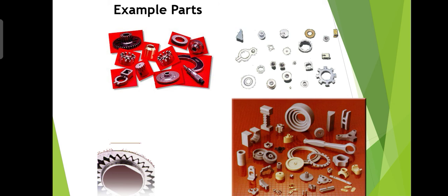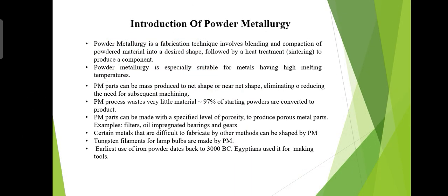components are the metal powders, and several techniques have been developed which permit large production rates of powdered particles, often with considerable control over the size ranges of the final grain population. These consist of fine, high purity metal powder produced by processes such as atomization, mechanical comminution, chemical reduction, electrolysis techniques, and agglomerations. These are the basic mechanical processes that are used to produce the powder that is used to make the powder metallurgy products. We will discuss this topic in our next lecture.